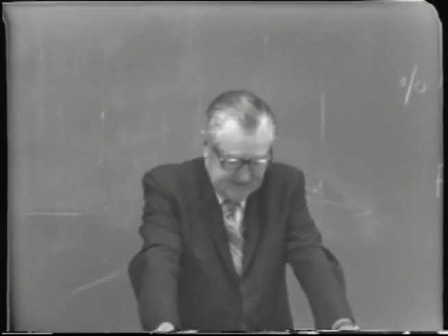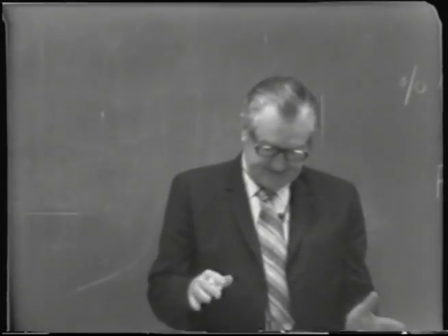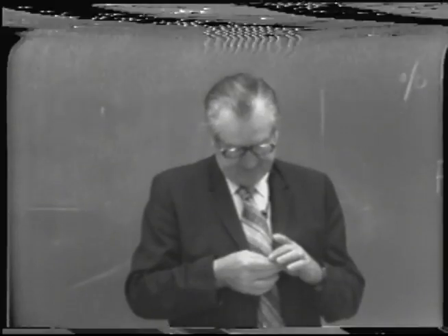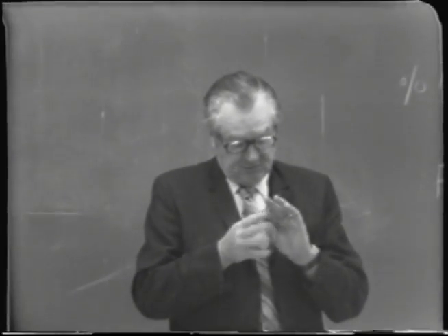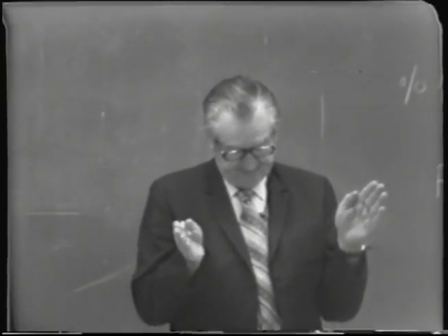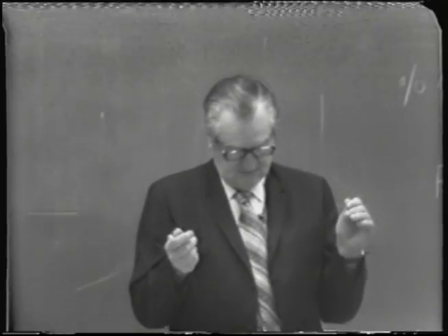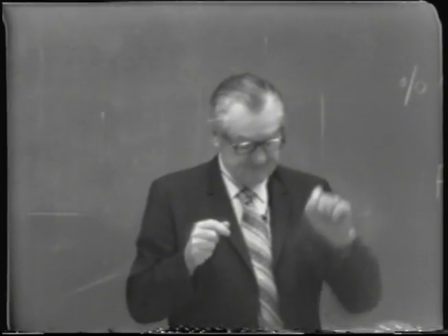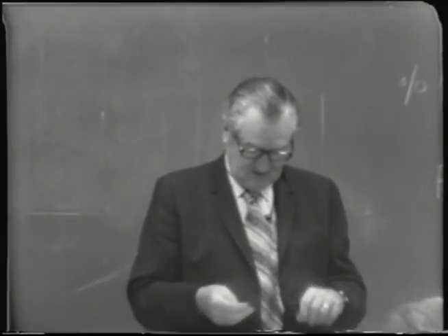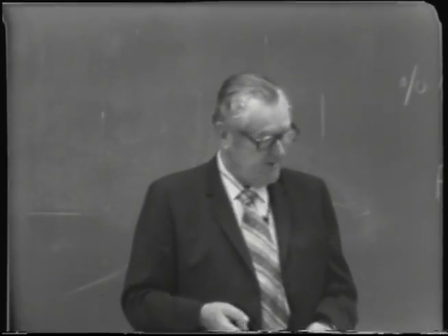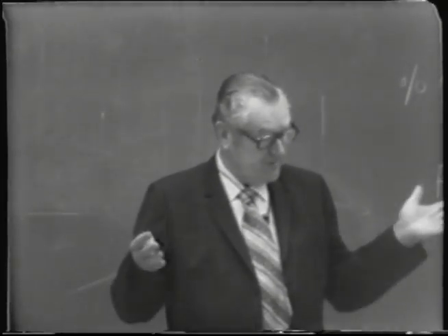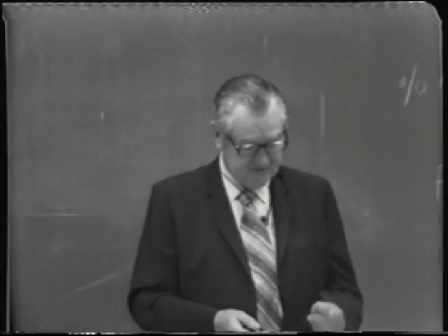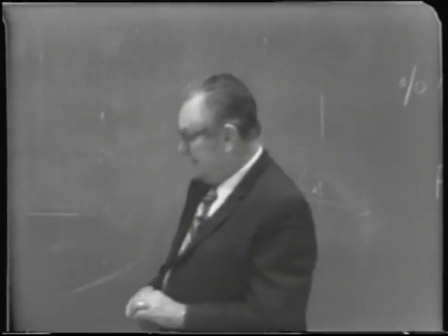Or you might say it this way: the number of equilibrium or ideal stages required depends on the degree of separation specified, that is, the specifications of the products, top and bottom, and the thermodynamic behavior, the vapor-liquid equilibrium relationships of the components in question. Of course, that has to come into it.